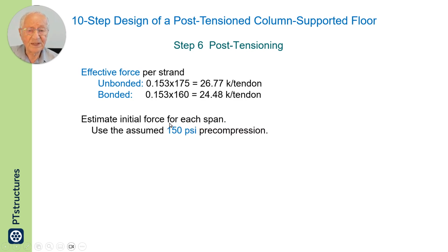So the force per tendon is known, and with 150 psi, I can work out how many tendons I need, looking at the cross section of the slab.